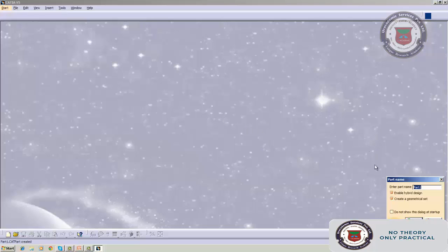You get a screen like this. Okay, so here the part name, we can give any name. Say we can change it into A-01, or we can say block, housing, anything. We can give a name of up to 250 characters, but we are not giving that much here. Here, enable hybrid design, create a geometrical set, and do not show this screen means you can click it, it will not show, and directly a sketch screen will open.